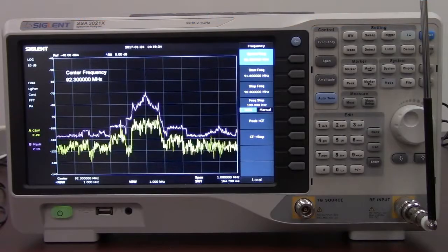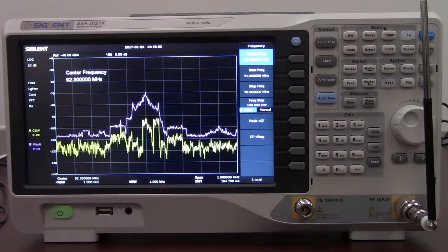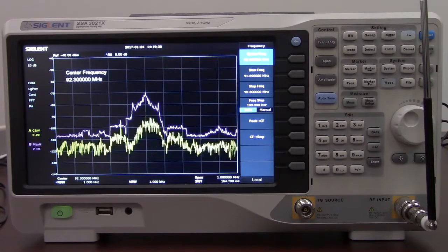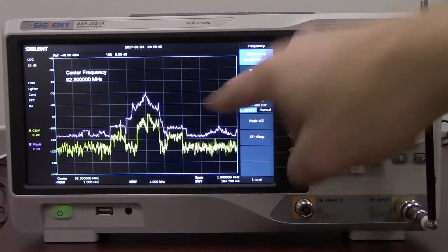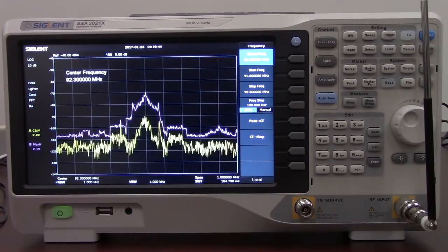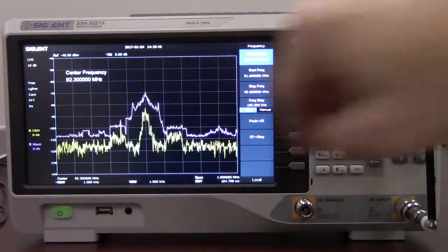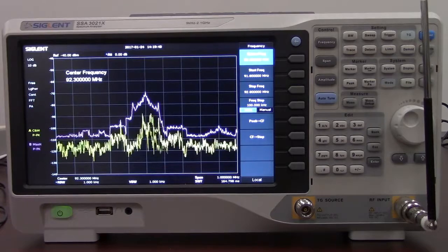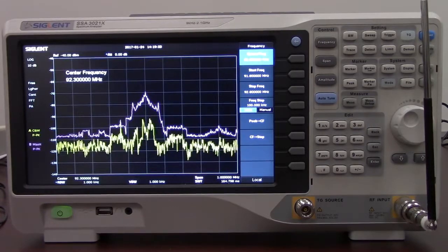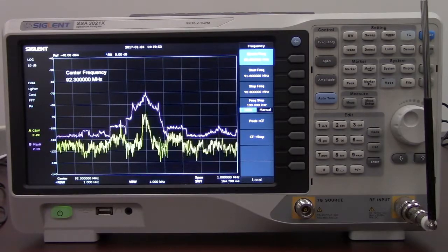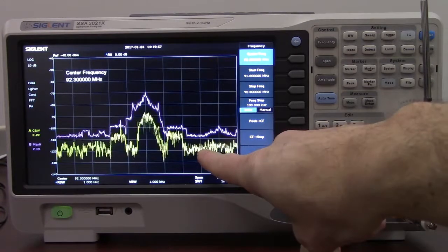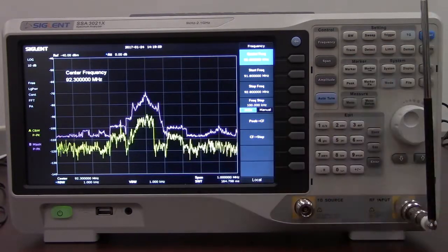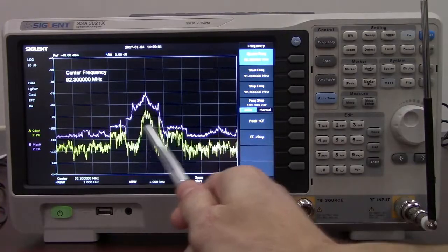For monitoring broadcasts and transmissions, I wanted to set up a little bit of a demo here in which we have an FM antenna, and we have this spectrum analyzer set to 92.3, which happens to be a radio station here in Cleveland, Ohio, and it's an FM radio station. And what I'm showing is the yellow trace is actually outlining the FM. So this is the FM voice section.